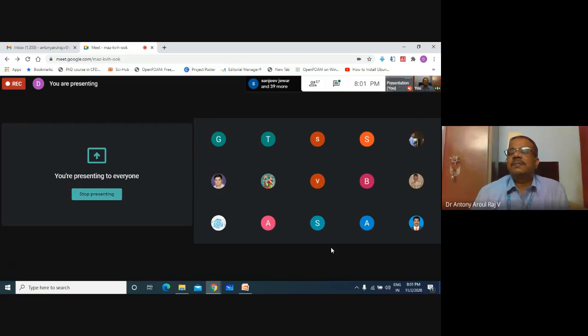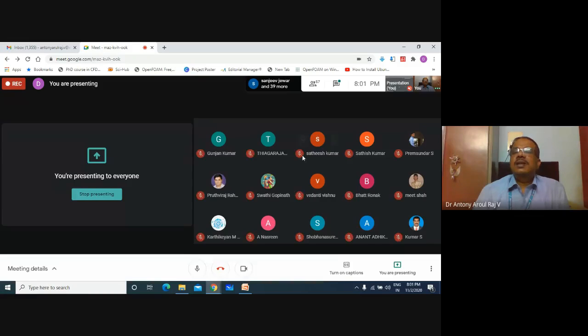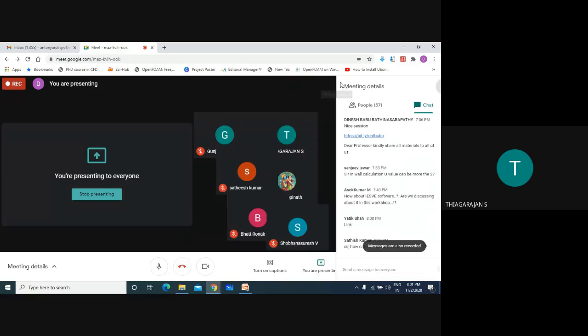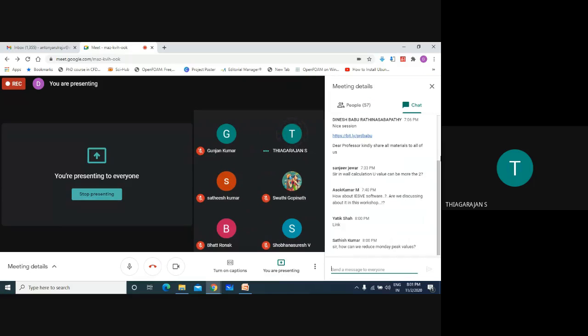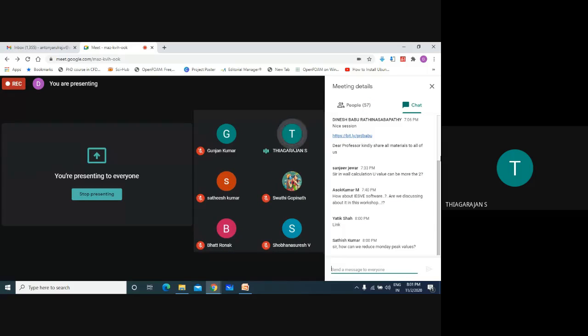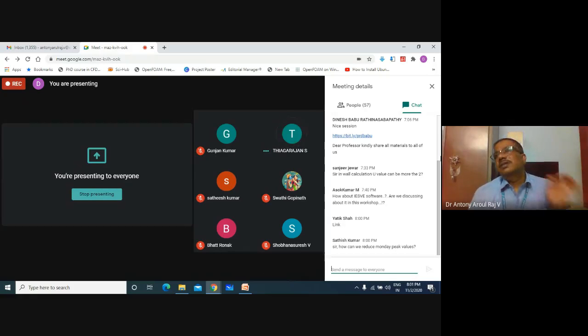Okay, yeah. So there is a question in the chat. How can we reduce Monday peak values? I think you can ventilate at nighttime. You can do the ventilation. That should be an automatic night ventilation, because you are finding nighttime temperatures. If they are lower, you can do nighttime ventilation so that the building's inside temperature can go down.